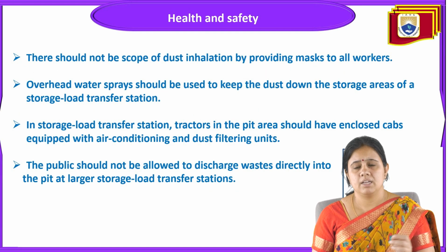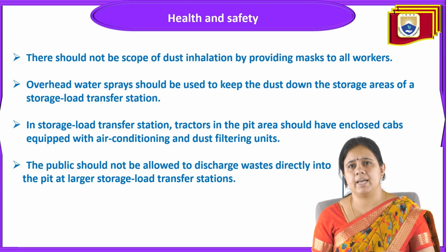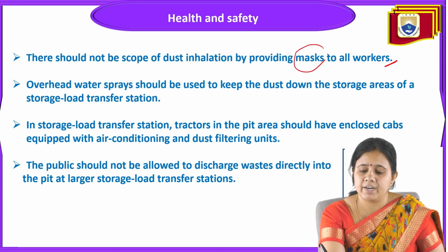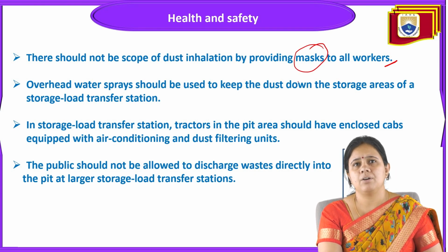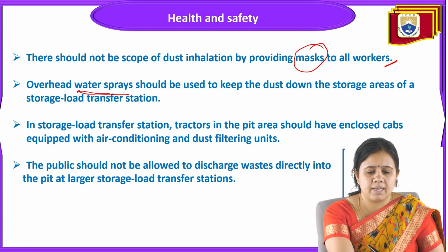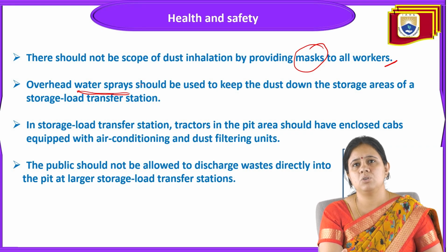Now we come to the health and safety point of view. From the health and safety point of view, there should not be any scope of dust inhalation, by providing masks to all workers. Overhead water spray should be used to keep the dust down in the storage area of the storage load transfer station.